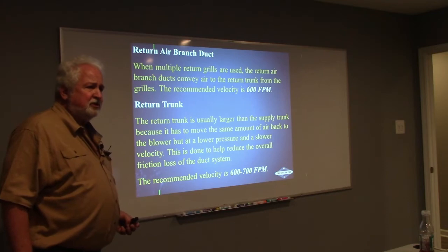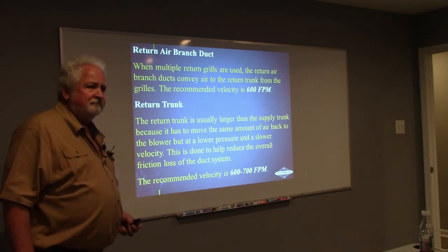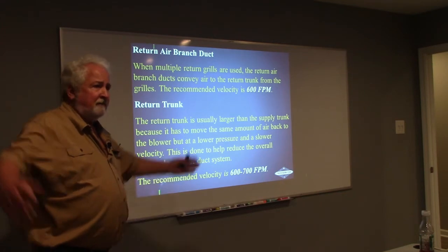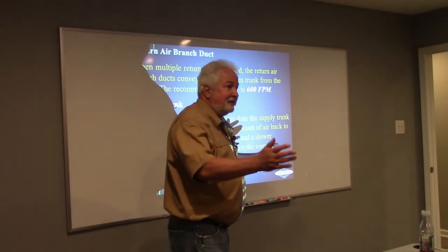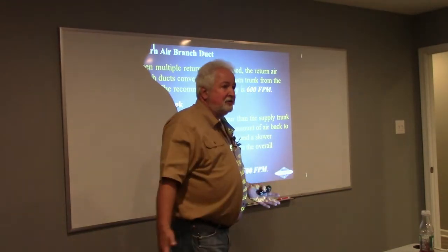Can I have too much return? Because it's a blower, it was designed to blow. If I've got this much air available, it's just going to take whatever it takes, right? Yeah. So you can't make the return too large.